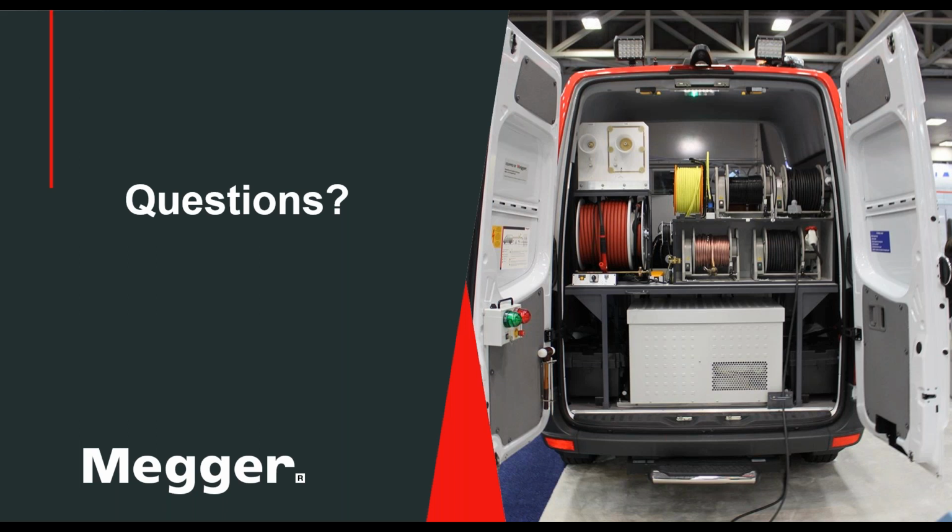You know, there are a couple rules you can apply. If you have two faults and one of them is a dead short, you must always repair the dead short before you can find any second fault. If you have a two-fault scenario, let's say with a pinhole and a burn in the clear conductor, then you might find the open point from the burn in the clear, and you find the pinhole fault, because the burn in the clear will not flash over, where the pinhole will flash over, following the principle that Marshall was explaining, following the path of least resistance.